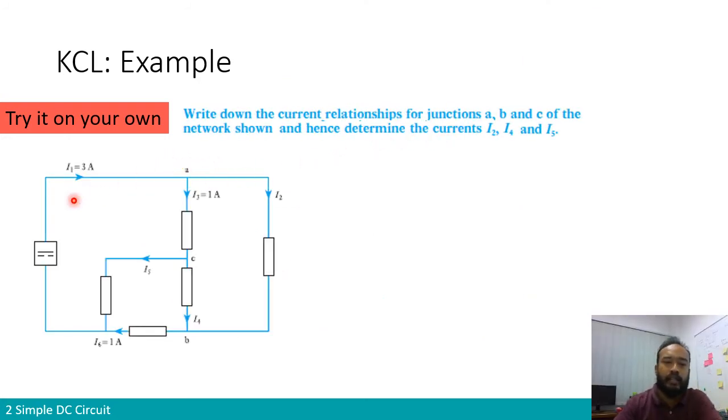So this one, the network is a bit larger. You have multiple elements. So this is the DC power supply. What we have is a current. As we mentioned, KCL is related to calculation of current, so we don't need to identify what the voltage is. If it were given a voltage, then you would have to deduce what the current is, right? So this one is pretty simple. The current is given. So we have multiple nodes.